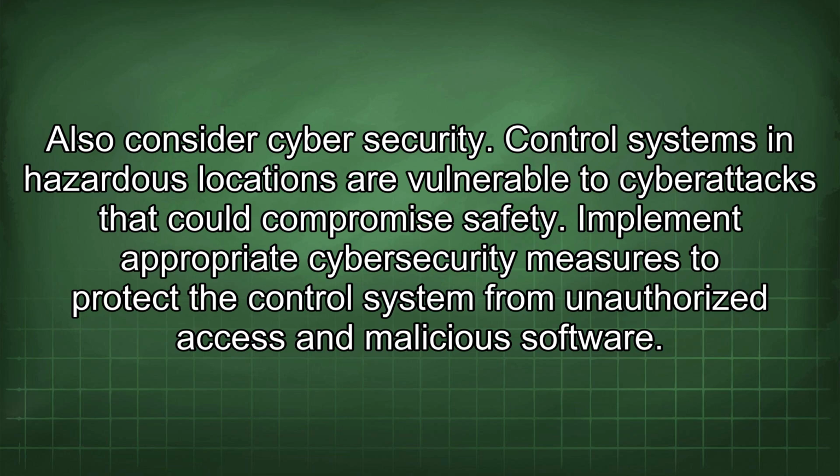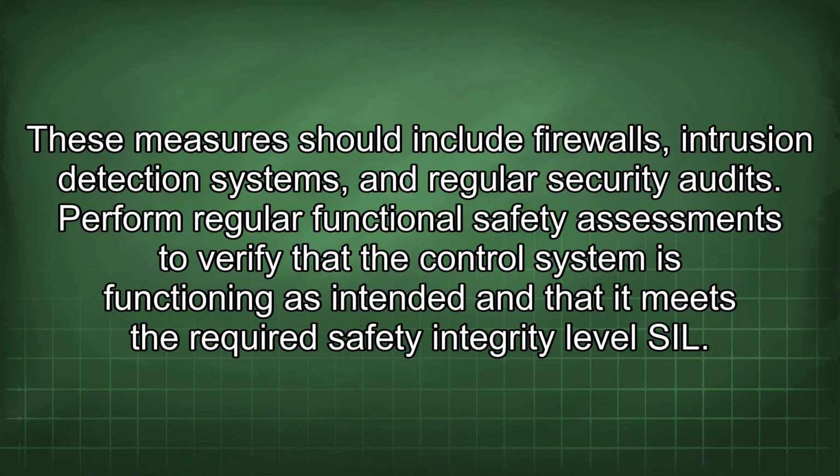Also consider cybersecurity. Control systems in hazardous locations are vulnerable to cyber attacks that could compromise safety. Implement appropriate cybersecurity measures to protect the control system from unauthorized access and malicious software. These measures should include firewalls, intrusion detection systems, and regular security audits.